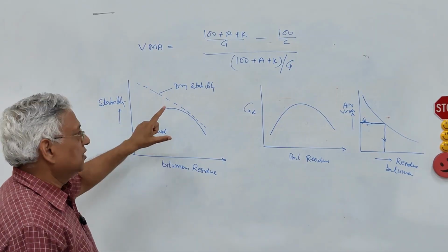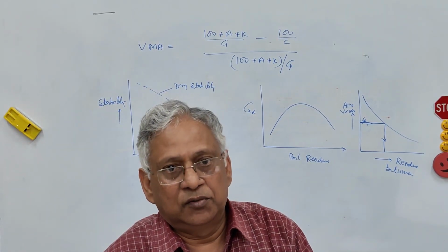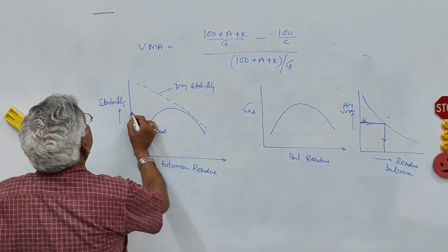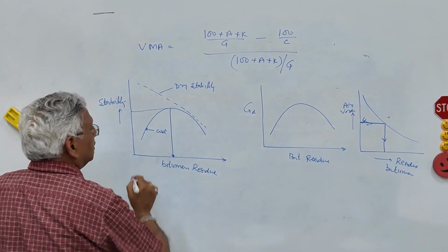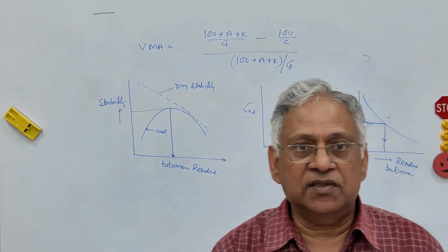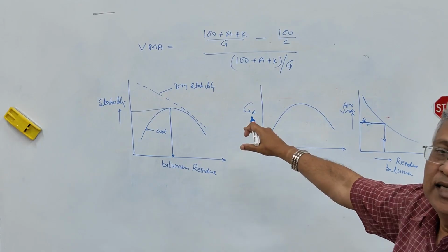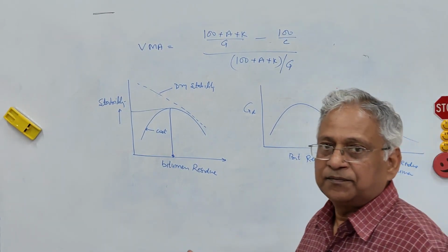Now, stability should be at least 2.2 kilonewton at 22.2 degrees centigrade. So that is the highest value here. You can make some adjustment within the air voids because the range is 3 to 5%, so that you get as close to maximum density as possible. So that is how you design the mix.